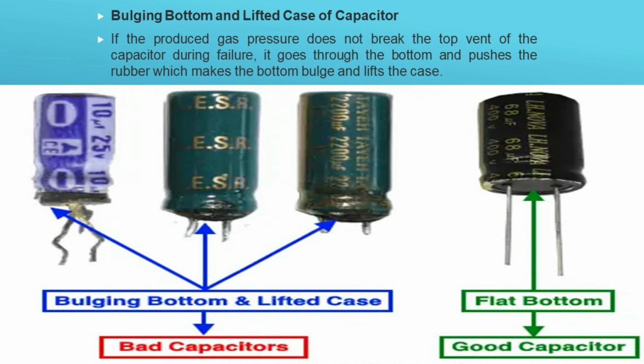Disconnect the power supply and remove the capacitor from the circuit board. Fully discharge the capacitor using a resistor. Rotate the knob and set the multimeter in continuity test mode. Make a contact of the positive, red, probe of the multimeter to the anode, plus, and the common, black, probe to the cathode terminal of the capacitor.